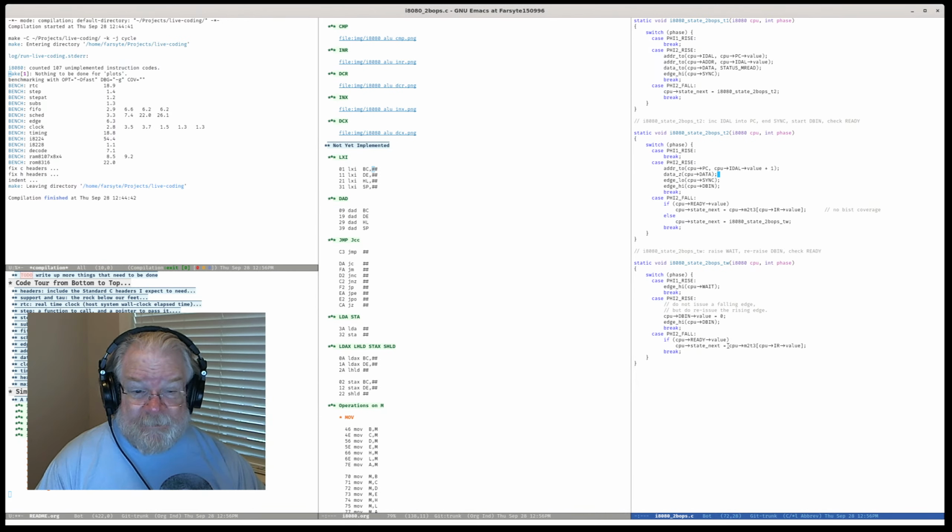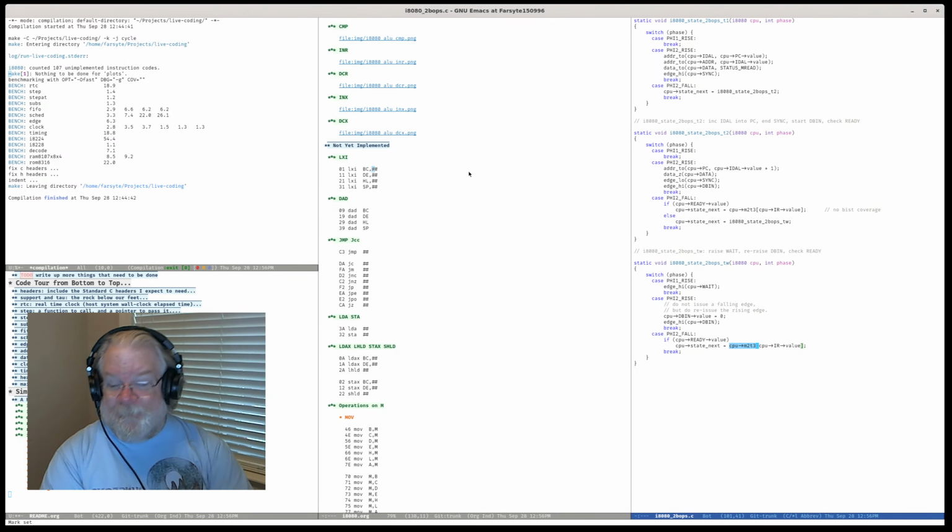We're diving specifically through CPU arrow M2 T3. Well, these LXI instructions want to do something different on machine cycle 2 versus machine cycle 3. So I need to have a way of saying I'm doing a machine cycle 3, which is going to call this other thing.